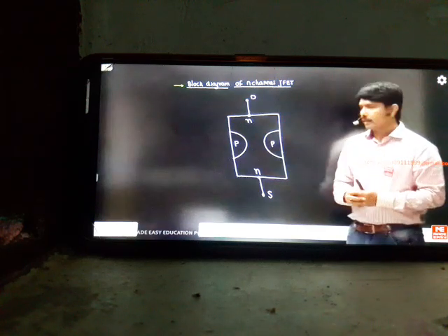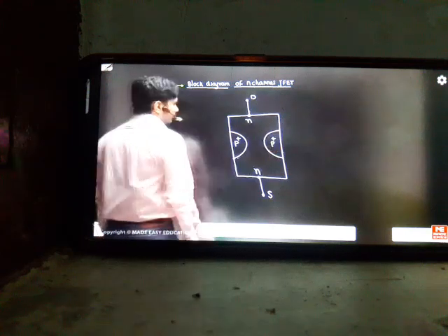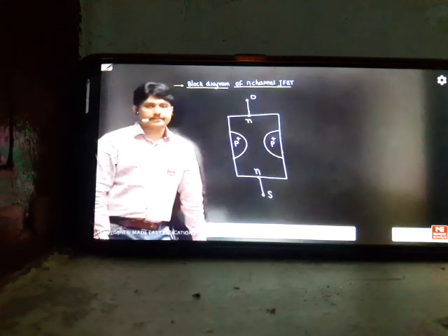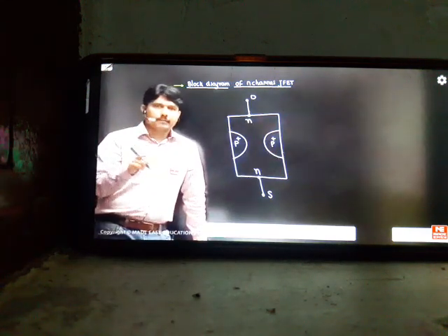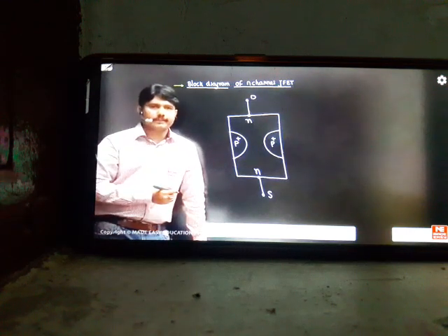Having equal doping is wrong. You always take some extra doping, which will dominate the N material, which will then behave like a P material. This is the rule of compensated semiconductors, as we call it in semiconductor devices. Always, when you add a new material into the original material, the doping should be higher than the previous material. Only then will it behave as a P material in the device. That's a very common rule.